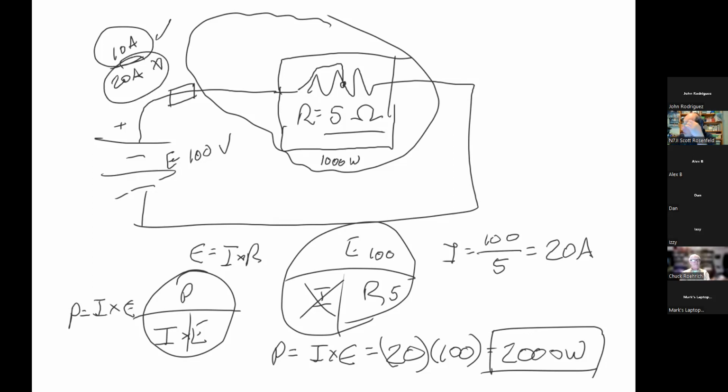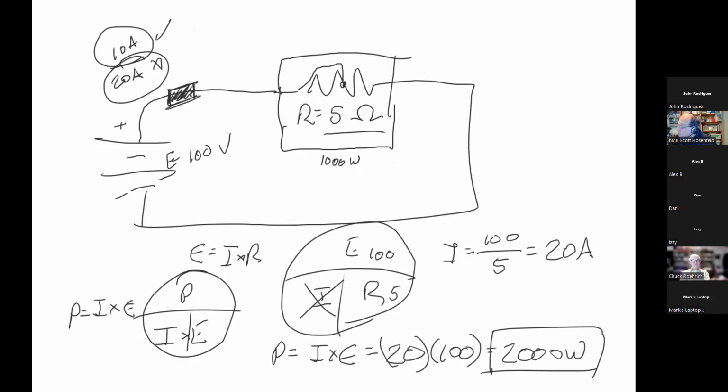what we can do is throw a device in here that is defined as a sacrificial element that will kill itself and thereby protect your house if there's too much current. Anybody know what this is called? A breaker. A fuse. A circuit breaker? They're both right. So this could be a circuit breaker or a fuse. And essentially, that is a device that is designed to heat up when the current gets too high. This is an overcurrent protective device that's designed to protect your circuit.